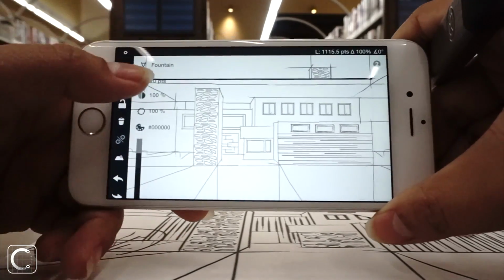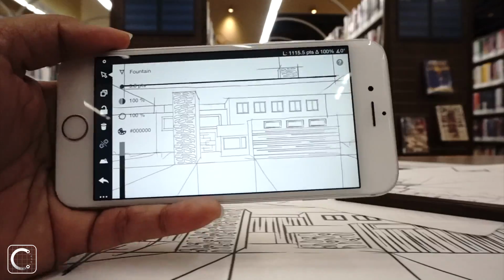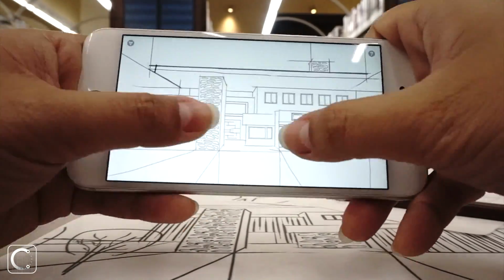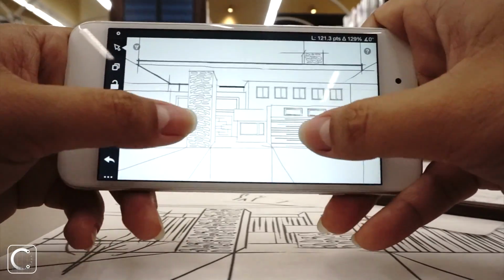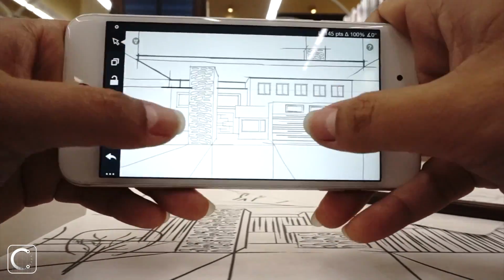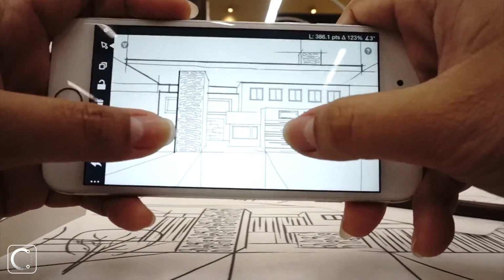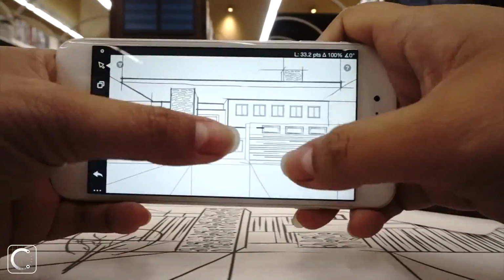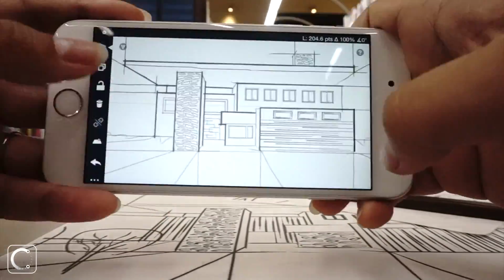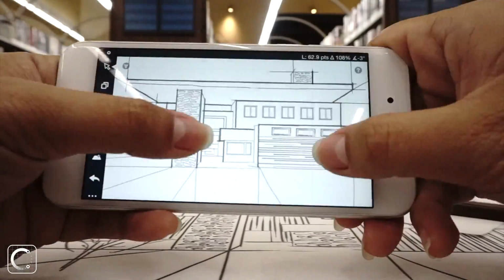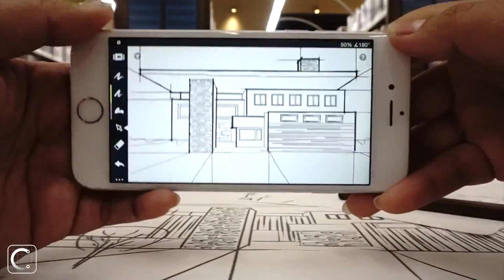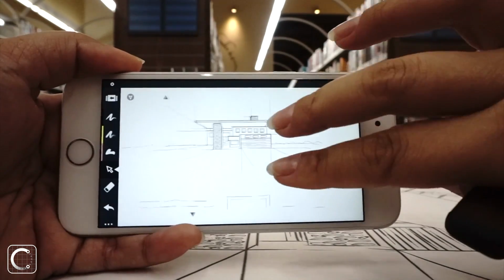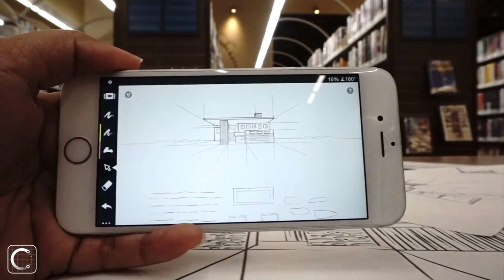In architectural sketches, a general rule of thumb for line weight is that your thickest or heaviest line weight will be over the parts of your building that touches the air or space in reality. So a good rule of thumb is the parts of the exterior walls that touch each other, you don't add the heavier line weight to. We also don't need to add thicker strokes to the base of the building because literally it's touching the ground.